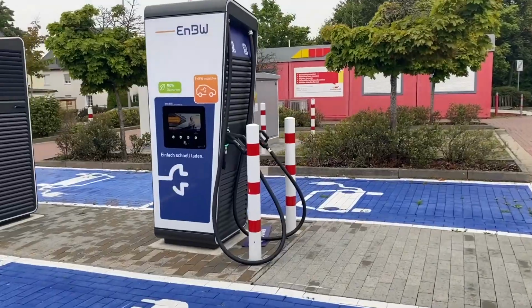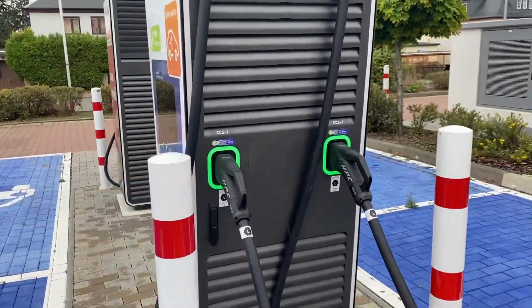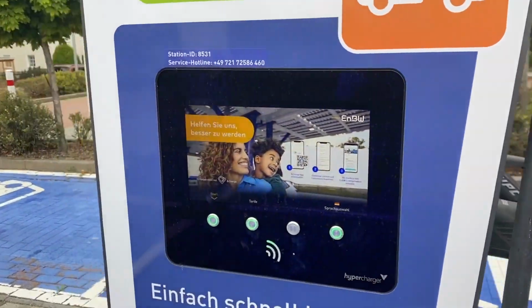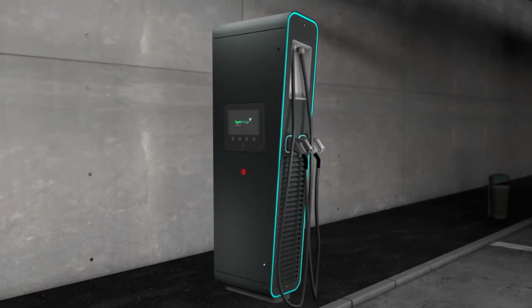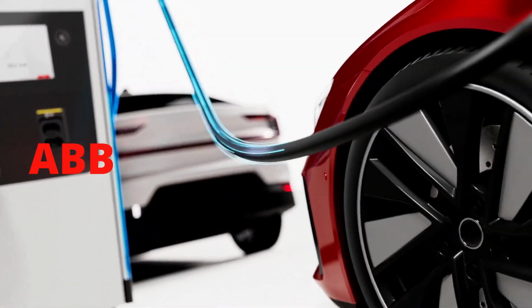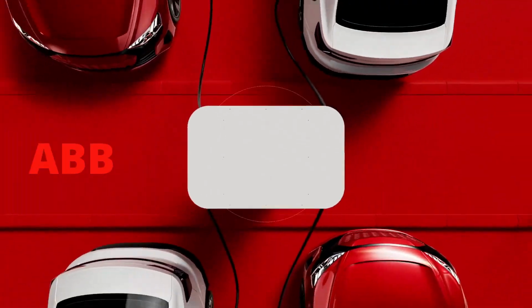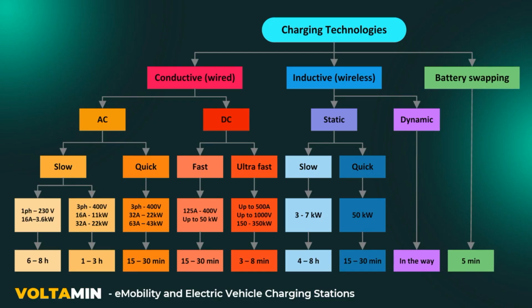They are commonly called charging stations and are managed by the charge point operators and used by electric vehicle drivers to charge their vehicles. Charging station systems include the electrical conductors, related equipment, software, and communications protocols that deliver energy efficiently and safely to the vehicle. EVSE equipment is classified from many different technical perspectives, which we will discuss in detail in this video.